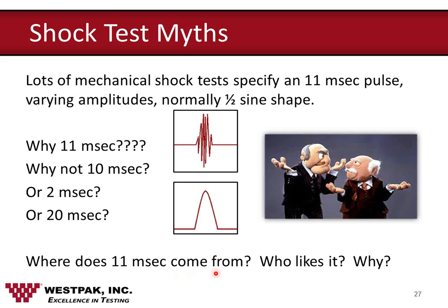And that's about as good an excuse as I've heard about where this 11 millisecond comes from, some old mil spec testing. So don't fall into the trap of thinking that you have to go to a mil standard and use their 11 millisecond duration. It really has no particular value other than it sounds good, I guess.